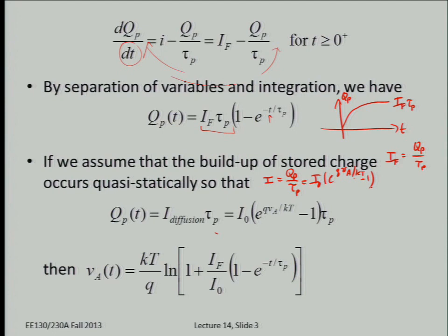It's very simple. It's nothing tricky, I don't think. Yes? Yeah, but so maybe it's a little tricky. If the recombination lifetime is longer, then the carriers won't die out as quickly. So when you flow these minority carriers into the quasi-neutral region, they won't die out quickly, so it should be able to build up faster.